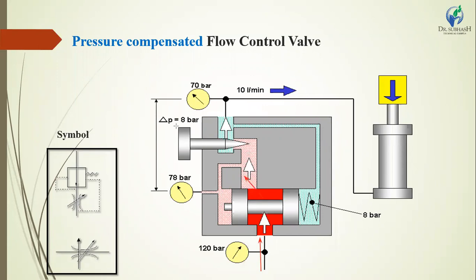Then this is the needle, with which we adjust the flow from inlet to outlet; however much flow any hydraulic system requires, we adjust it with this adjustable screw. That maintains the area of opening for this position. Then we can control the fluid flow.